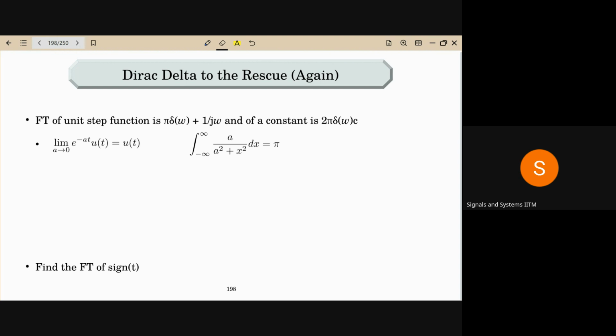So in order to check if the criteria is met or not being met, you'll have to know Laplace transform. The one statement that I made during the lecture, that all poles should be on the left half plane, is a very famous statement. That is one of the criteria that you will use if you're designing a control system with feedback to ensure that the system is stable. So you will almost day in and day out use that rule to design feedback systems in control system design and so on. So it often appears in circuit analysis.